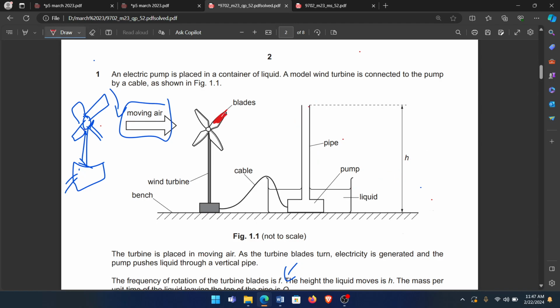Connect a pipe. But a very important thing is you cannot connect the outlet pipe in a way that H is changed. You are not measuring H. So connect a rubber pipe in such a way that H is not changed.